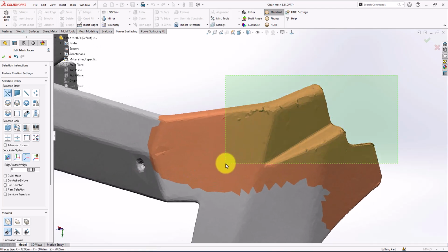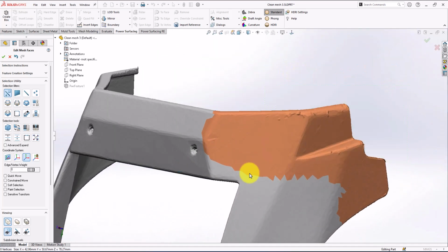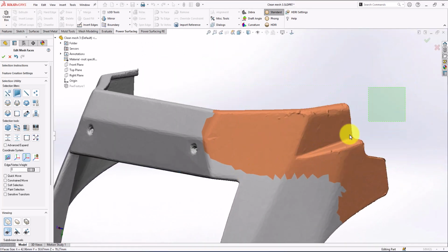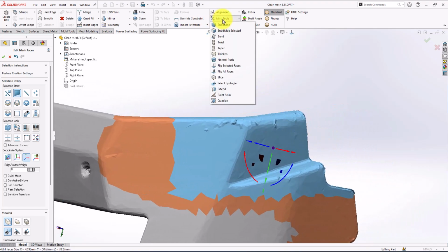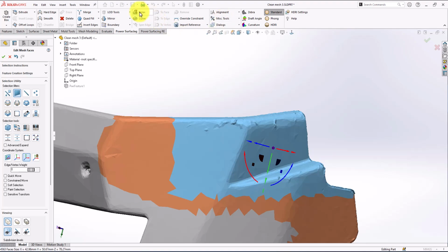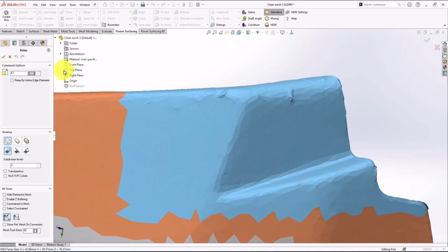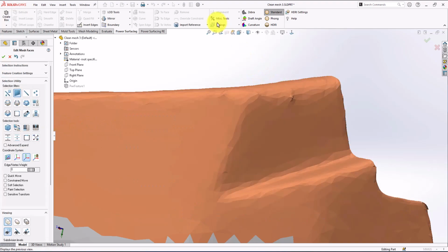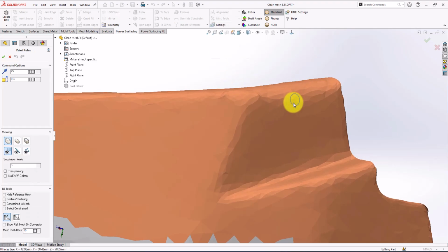It might be helpful if I just select this area with this face selection, then go to relax, as you see, but I'm not going to use 300, maybe less, so you can see it's smoothing the whole surface. So maybe just a little bit and apply, then get to your paint relax and fix these small distortions.